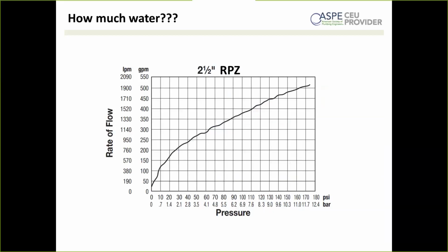So let's answer a question I'm sure you all are here to learn, which is how much water can come out of that relief valve. It depends on a number of factors. As we've discussed, the failure mode matters quite a bit. Basically, if the first check is fouled, how open is that debris holding that check? So how big is the debris that's fouled that check? Valve size, valve make and model matter, as well as the pressure the zone is being exposed to.